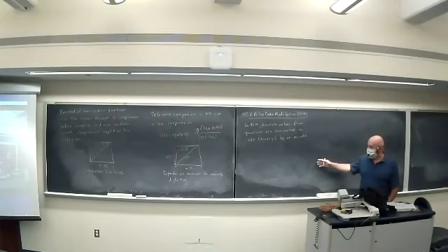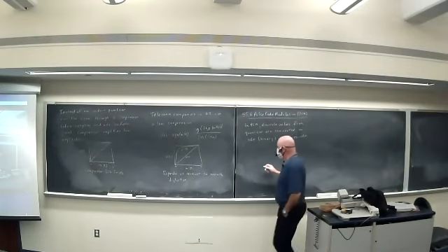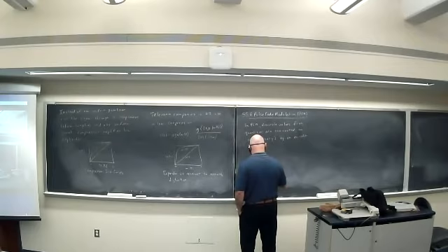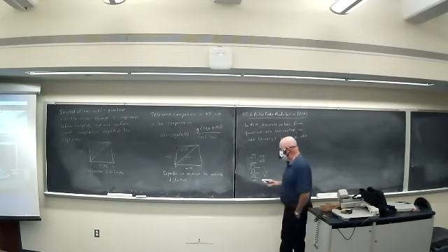So for 2 levels, you need essentially 2 pulse amplitudes, right? For 4 levels, 2 bits in a single pulse, you'd need 4 different amplitudes, right? I could map this to a 0, and then no pulse to a 1. Alternatively, it's usually done like this. Alternatively, if I used 4 different amplitudes, I could get 0, 0, 0, 1, 1, 0, and 1, 1.